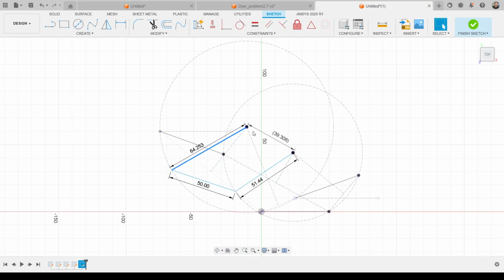To do that, we will continue working on this sketch, because we need a lot of the information that is here. So I won't create a 6th sketch. I will continue on the 5th one. So let's create one line that will define one of the 2 limiting positions for our 4-bar mechanism, and that's one of the requirements, right?